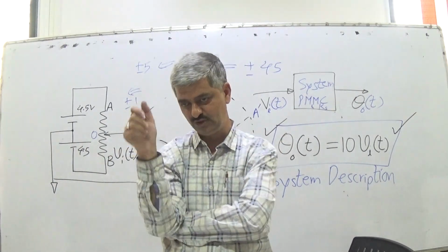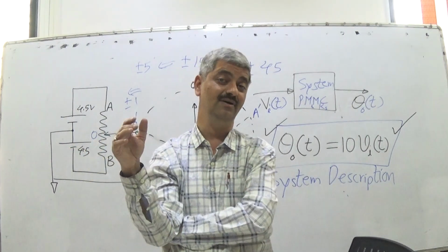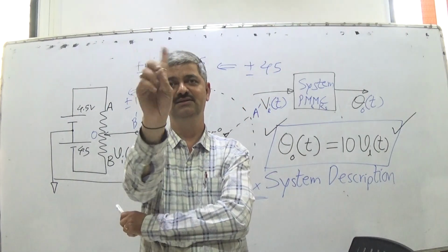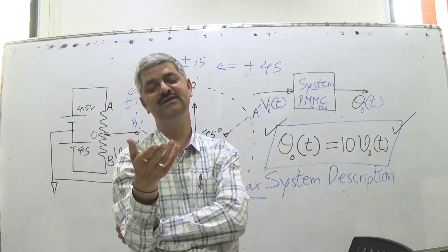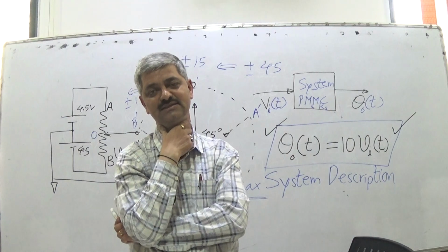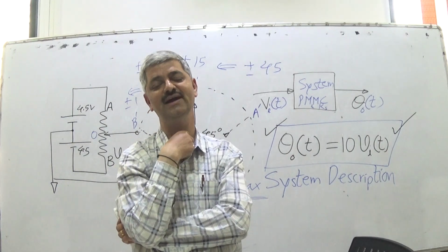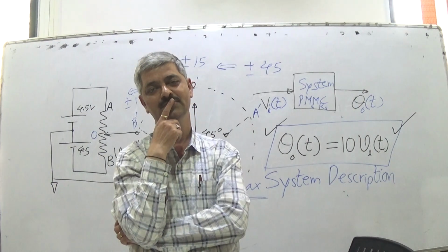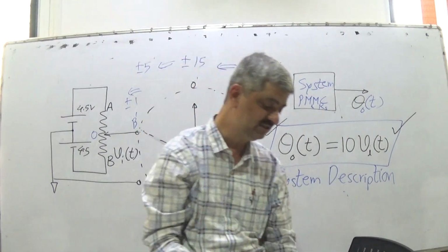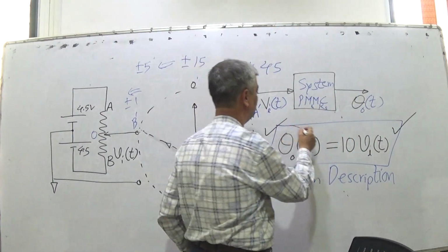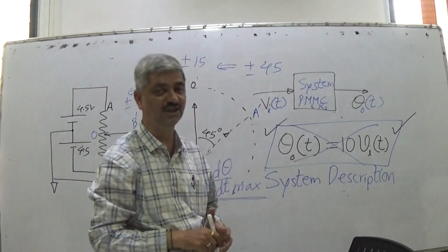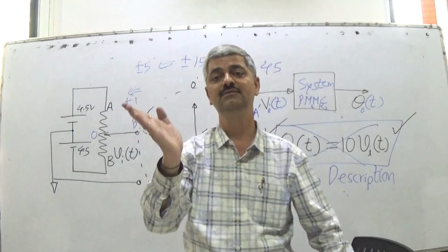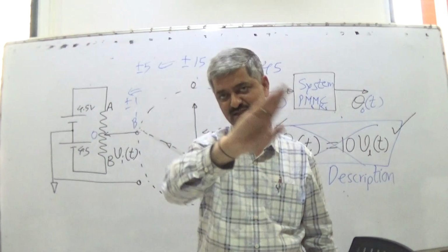You can change voltage using a potentiometer, or you can have a sinusoidal generator. You can give some frequency in kilohertz or megahertz, and you will find that if the frequency is too high, it is just like a center zero DC voltmeter with AC input: it shows steady at zero, just vibrating to a small extent. So the conclusion is, this system description is wrong. Such a system cannot be created. Why? Because of the physical limitation of the deflecting coil, spring and all those elements.